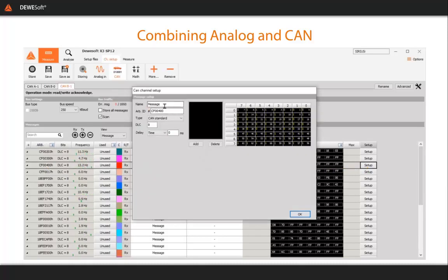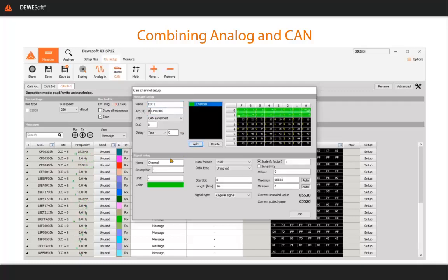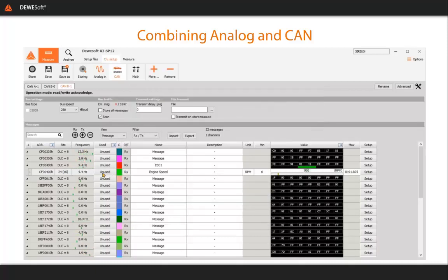So now I've identified that I'm pretty sure that the F004 we spoke about before, the EC1 message, is available. So what we do first is make sure we have selected that message, because it's being broadcast, since we use the scan option. And then we know that engine speed is located at bit 24 and it's 16 bits long, and that the scale factor is 0.125. You can probably remember that from the previous screen showing the blue book.